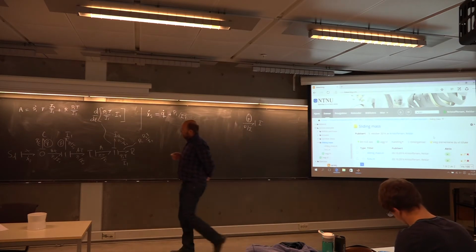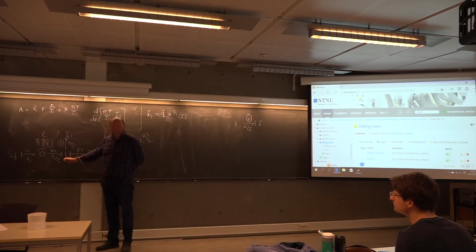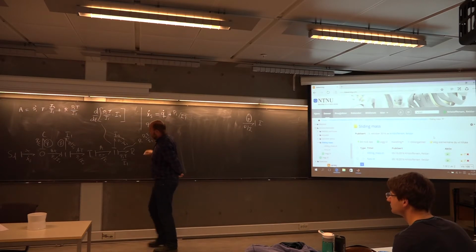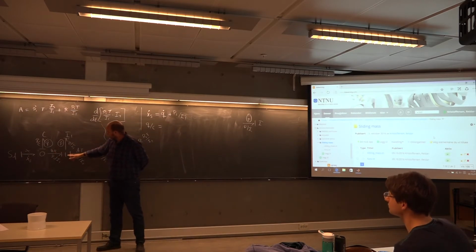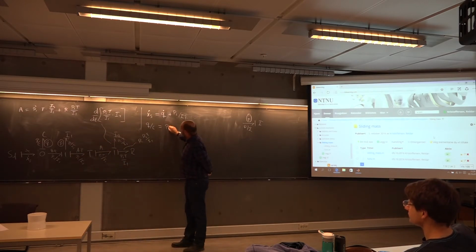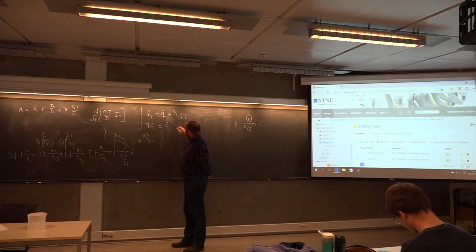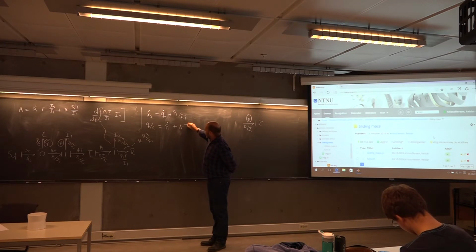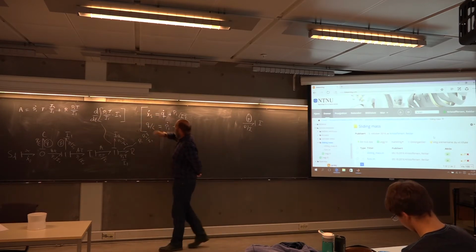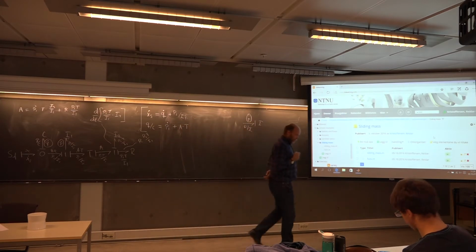And the final summation, sum all the efforts around this one junction and get 0. So the effort in, that was Q over C, goes in, equals what comes out. Well, that has to be P1 dot, and then plus coefficient A there multiplied with T. So here I now have my 2 equations.